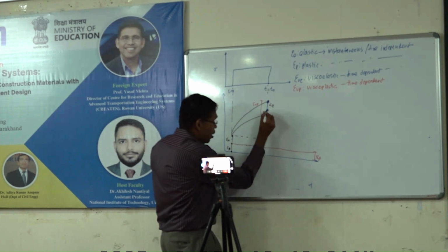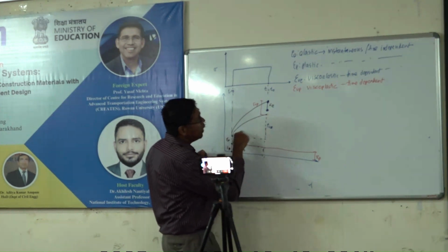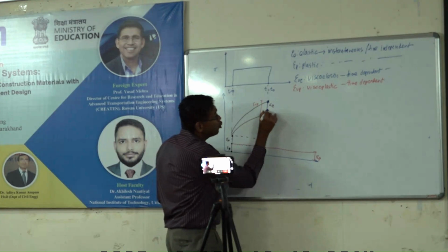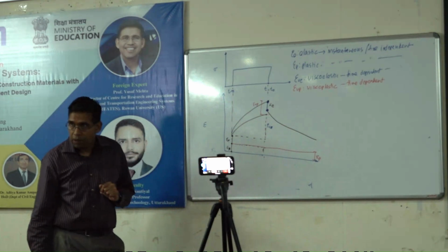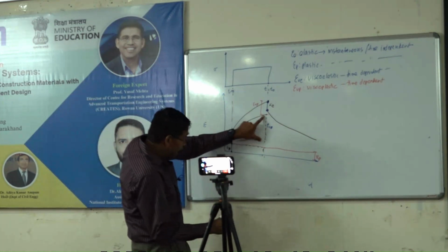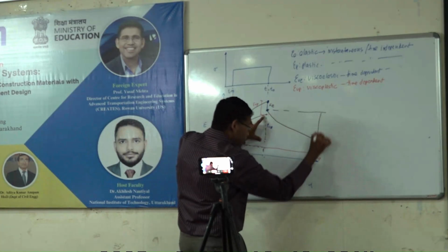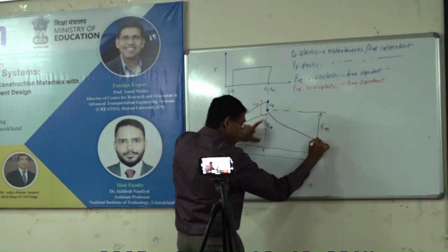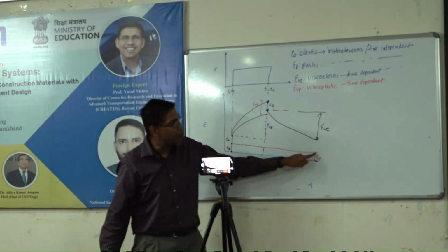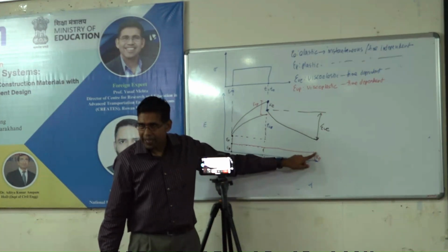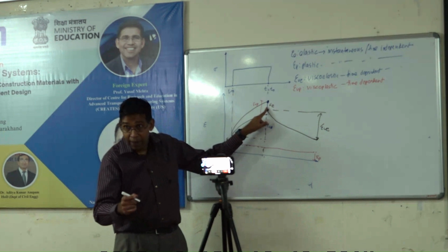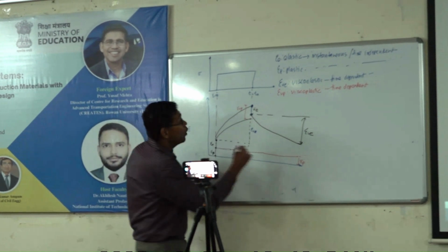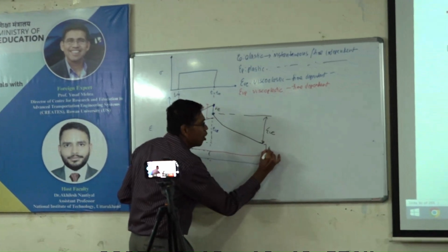Then the viscoelastic portion accumulated over time, and it will also come back over time. So this portion that accumulated over time, that same portion will come back over time. Why will it not come back to this? What is that? Yes, the viscoplastic accumulated over time, but because it is plastic or permanent, it will not come back and you are left with epsilon Vp.